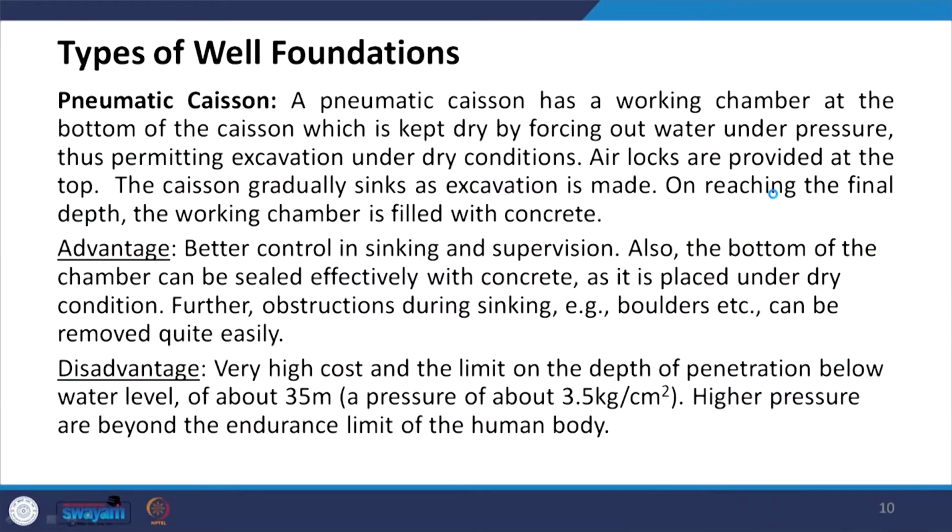So, this will work like a cofferdam also. Airlocks are provided at the top. The caisson gradually sinks as excavation is made. On reaching the final depth, the working chamber is filled with concrete.